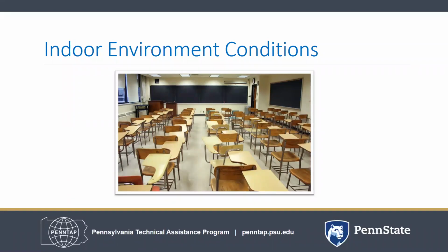Each place has a different job. Not all are the same and should therefore be considered when you're readying for implementation. While walking inside the building, use a temperature gun and make spot measurements to note the temperature. What is the typical temperature? Does it feel unusually dry or humid? Talk to the people in these rooms to get a general understanding of their comfort.